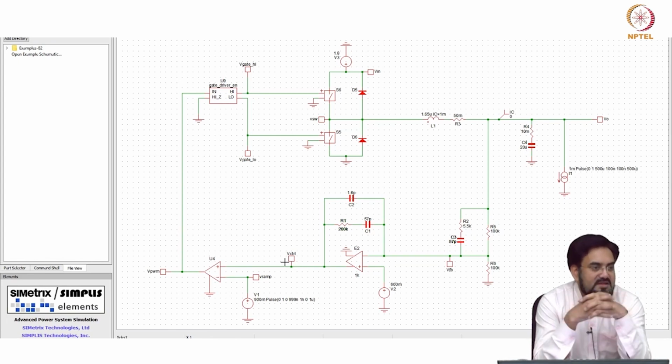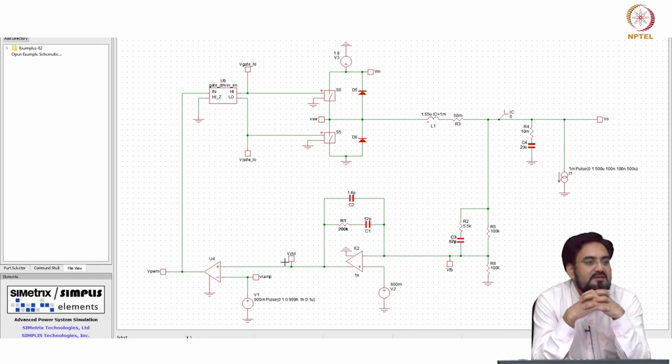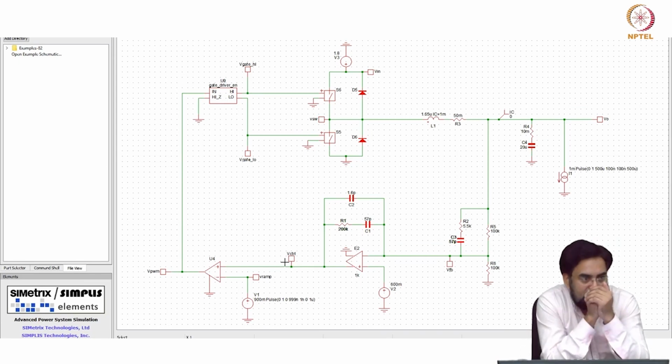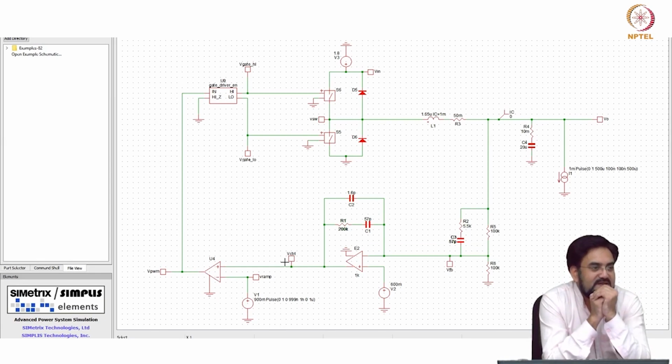It does not matter how large the ripple is. Then why do we care about this? No, this will not affect your output, because that ripple is filtered out by the LC. At 1 megahertz, your LC, with omega naught very low compared to it, will filter everything out. So you will hardly get a portion of that appearing.